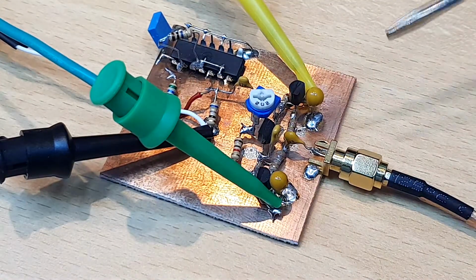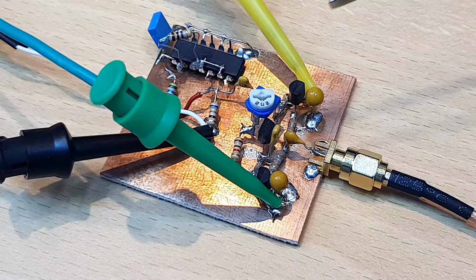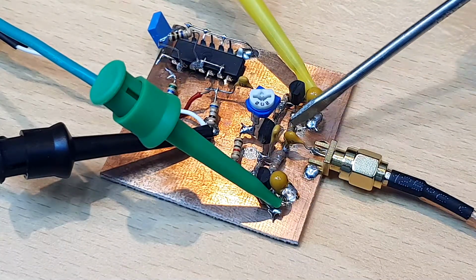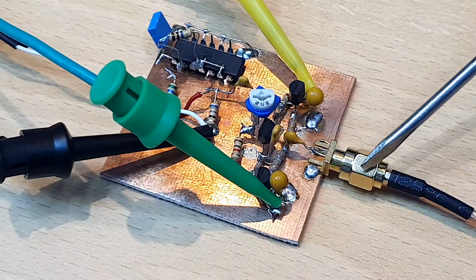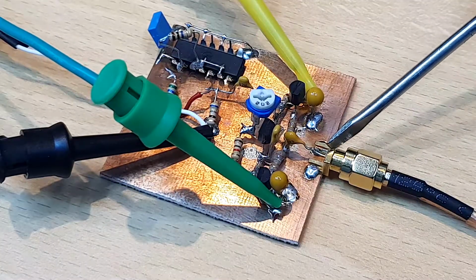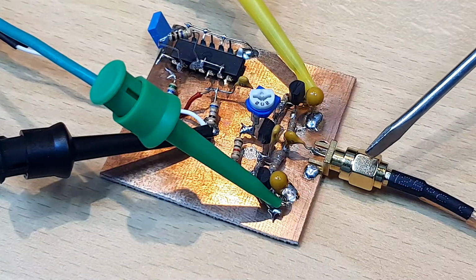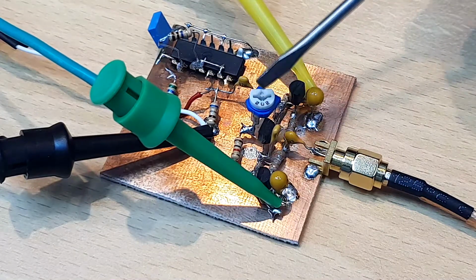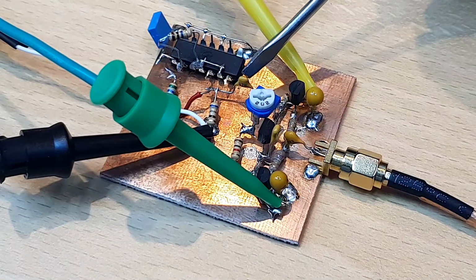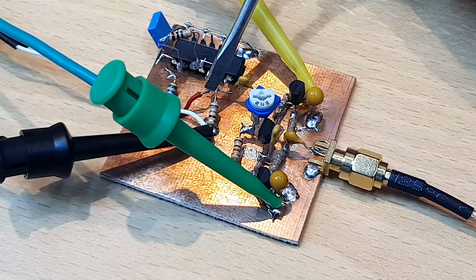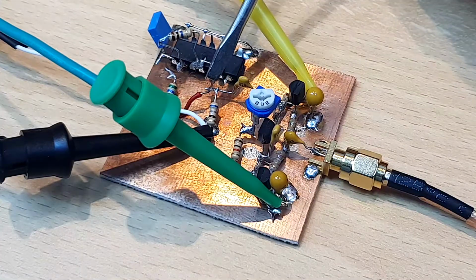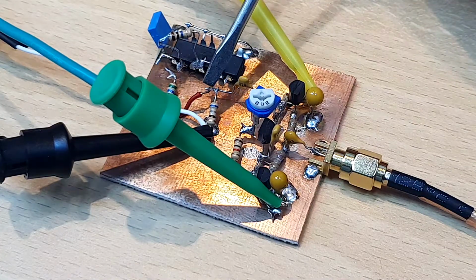So guys, this is the circuit I assembled here on the bench. We have here the two transistors, the NPN is here, the PNP is here. The output coupling capacitor is this capacitor here that goes to the SMA connector, to the SMA cable, to the 50 ohm load on the scope. Here we have the transistor of the VBE multiplier, the trim pot where you can adjust the biasing, the AC coupling capacitor that couples the input 1 meg signal, and here the 56 ohm resistor that terminates the line with an almost 50 ohm impedance for the signal that comes from the generator.